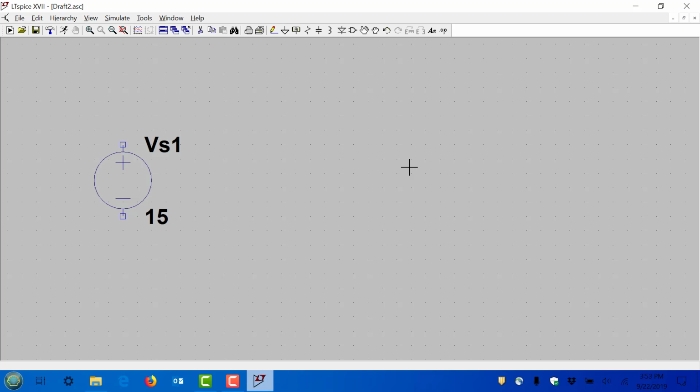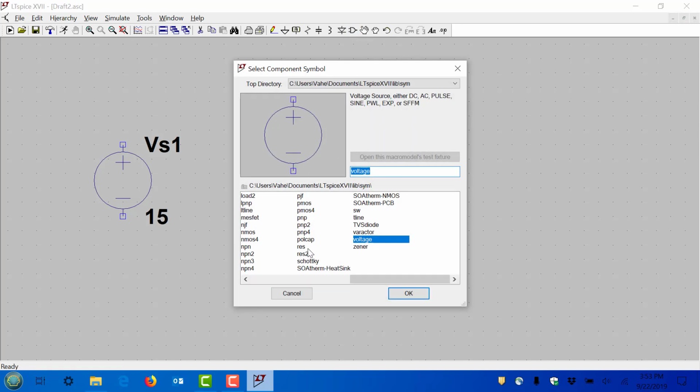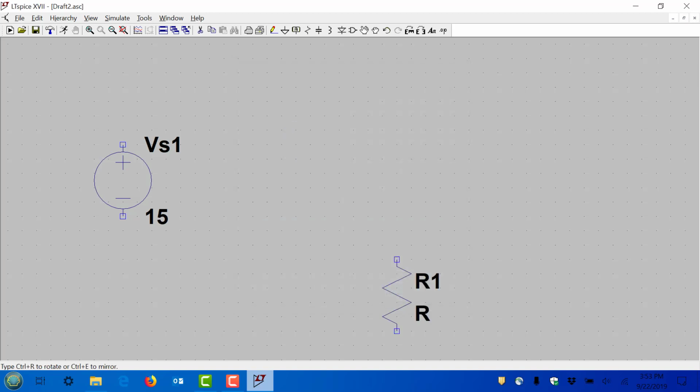Okay, so let's enter maybe a resistor. We can do the resistor entry 3 different ways. First, we can go back to the component and search for the element called RES. That's a resistor. There's also RES2. It just has more of these wiggles. I just prefer RES. So you could enter a resistor this way. Okay, so let's do that first. So you OK it and you say, okay, where do I want to enter this? Well, I want to have it horizontal, not vertical like this.